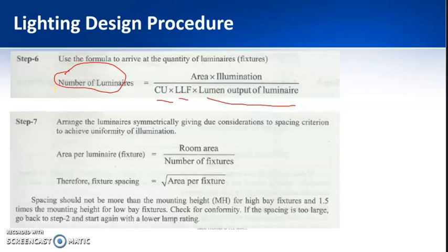Once it is done, then you need to arrange the fixtures. So the area per luminaire you can calculate from room area divided by number of fixtures.